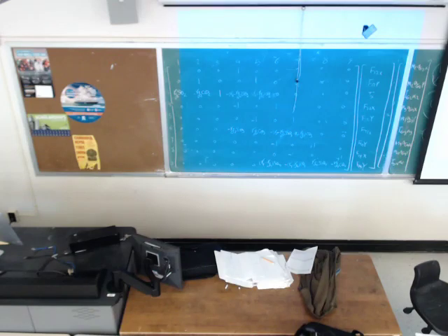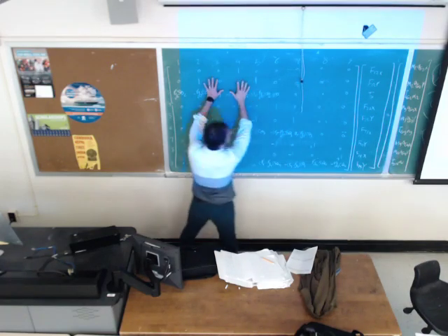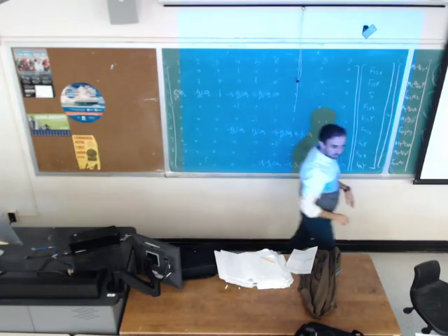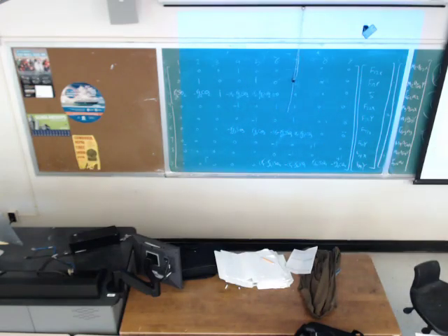Okay. So you need to use the loop: 360 divided by 5, it's going to be 72. You are going to solve this system of equations 72 times by the loop. And in each iteration, you will get a T. You are going to plot T versus theta for all 72 points. If you plot them, you will get something like this. Tell me what will be the maximum torque at which angle.